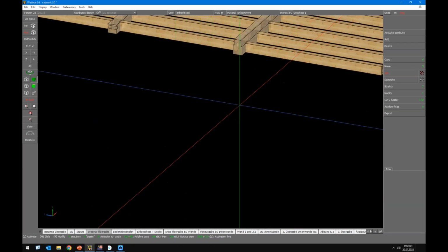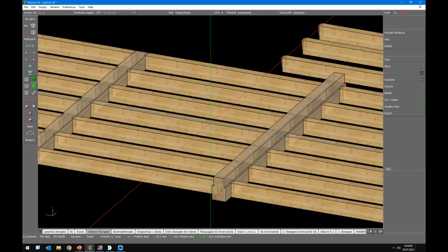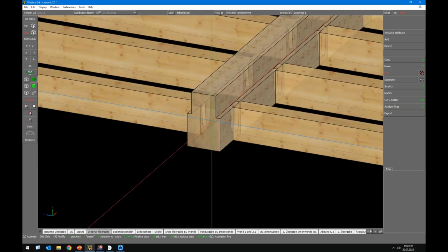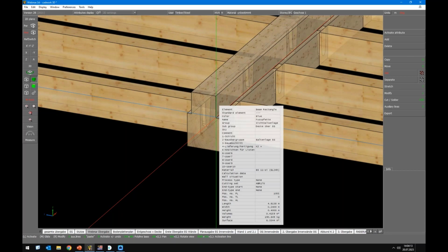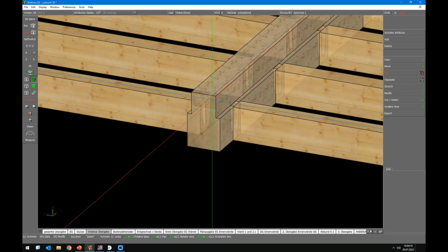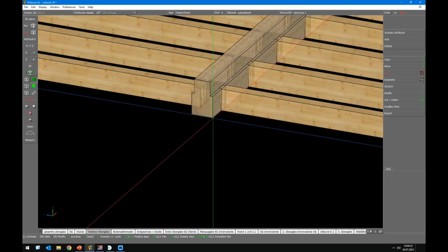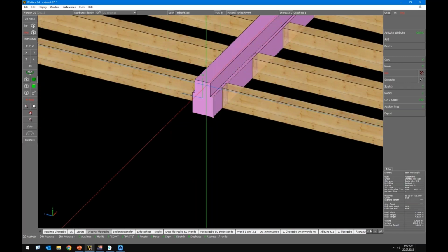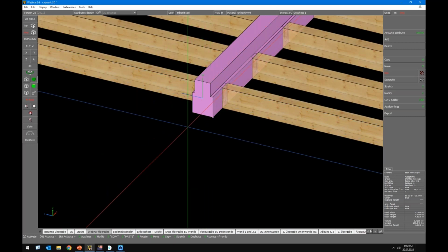So the ceiling beams are connected via dovetail connection, and the bearing beam will be a bit inside the ceiling structure. Otherwise, we would get too little stiffness. It was decided to lift this a bit up. Maybe not so good for acoustic reasons, but the building constructor decided to have it bottom to bottom for floor and bearing beam, or for this downstand beam or flush beam, however you call it.